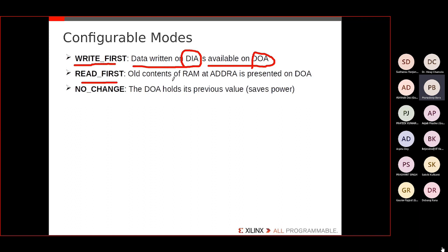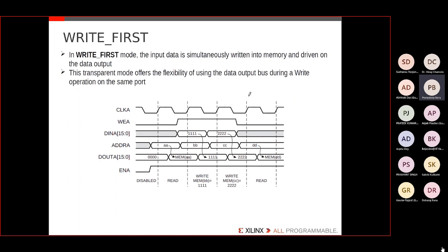Read first means whenever I am writing, if at that time I am reading, I will get the old contents of the memory. We'll discuss this using waveforms. And then we have no change. No change is like a power saver. Whenever I'm writing the data, the output will be latched. We'll see that in terms of a timing diagram.